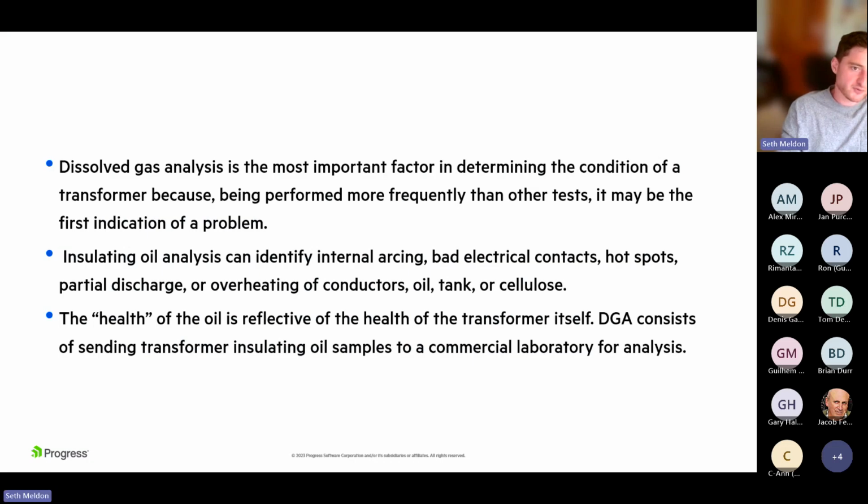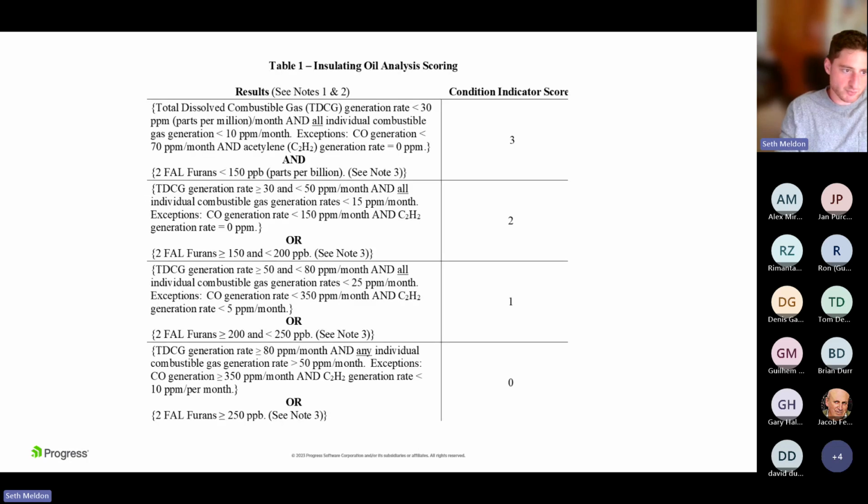This is one of the most important aspects of measuring this dissolved gas analysis, aka the oil analysis. Suffice to say that there are different types of oil used for the insulation between the different components of the transformer, in order to mitigate safety issues, but also to maximize the efficiency with which the electricity moves from one component to another, and ultimately out at a lower or higher voltage. So a lot of this is related to measurements that can be derived about just the oils being produced and given off by a transformer through a number of different test mechanisms.